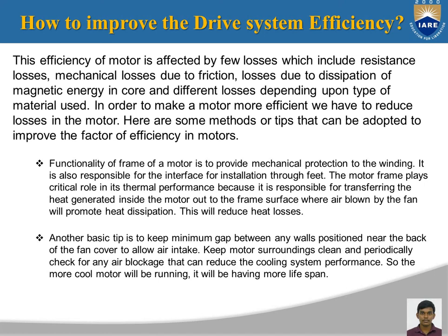The efficiency of motors is affected by a few losses, as I already mentioned, so we have to take care of this. There is some small hardware work, like the functionality of the motor frame, which is to provide mechanical protection to the winding. It is also responsible for the interface for installation through the feet. The motor frame plays a critical role in the thermal process because it is responsible for transferring the heat generated inside the motor. So we need to keep a fan, which reduces the heat losses.